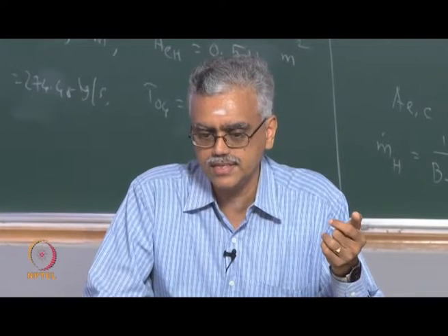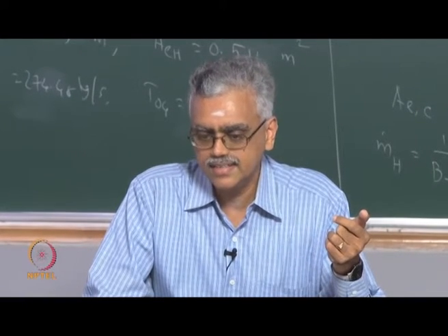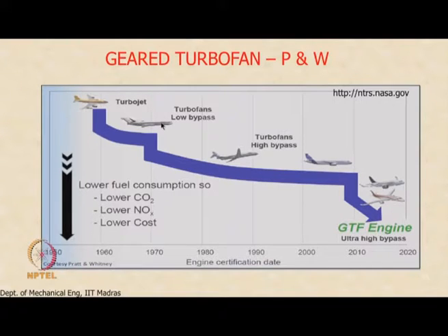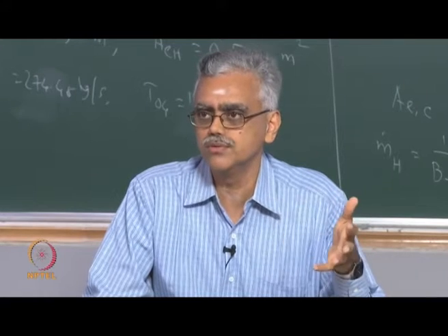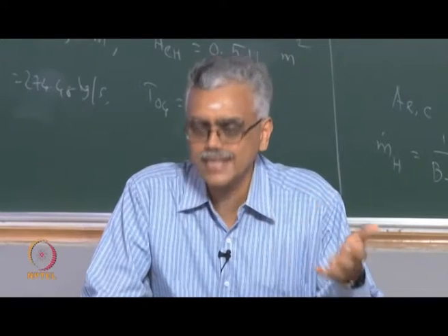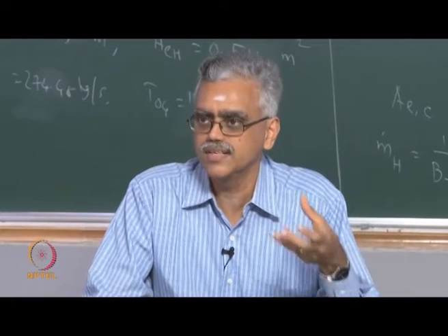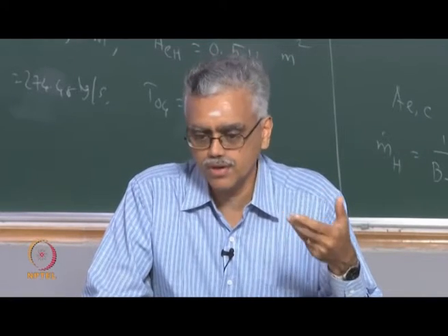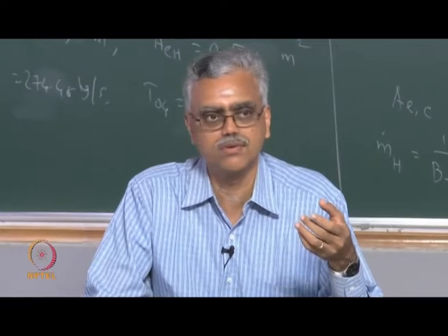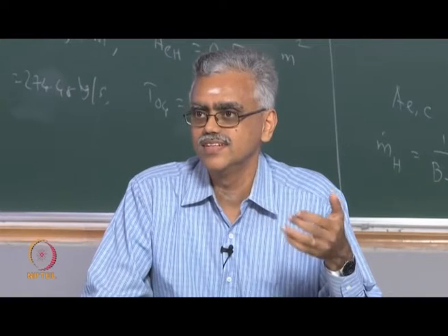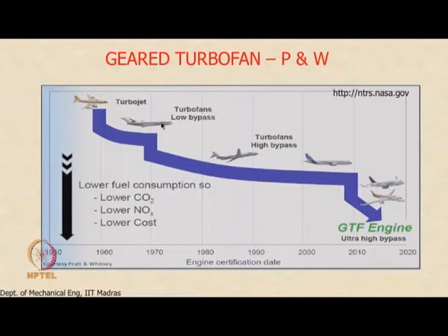So over the years, the high bypass turbofan engines technology relating to that has more or less stagnated, as you can see from here. This is a long span, okay? We are talking nearly 40 years. So the technology has matured and it has stalled. So no more gains in fuel economy or efficiency or emissions appear to be possible with the current technology, which means we are looking for a paradigm shift. If you will forgive me for using this cliche, we need a paradigm shift to realize bigger changes in fuel economy, and that paradigm shift appears to be the geared turbofan engine,